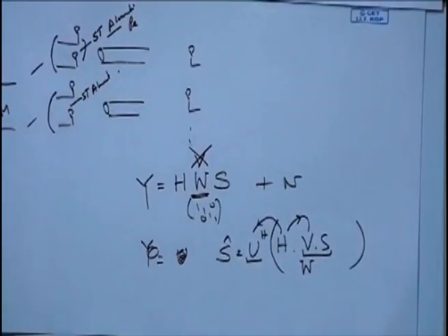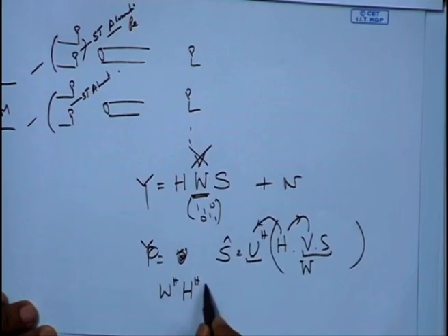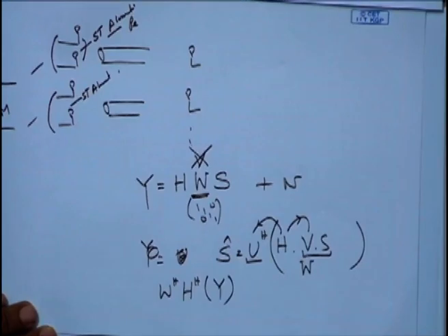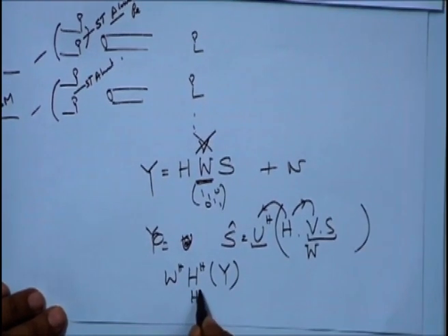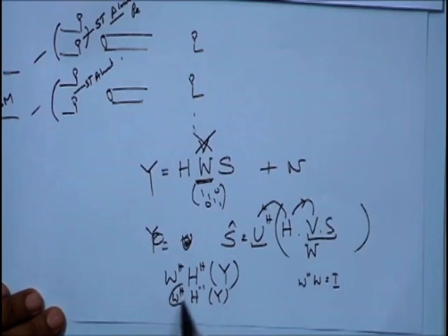At the receiver it is not a problem, because one of the easiest ways for a receiver is to multiply H Hermitian and then W Hermitian to Y. The other way I could do it is H inverse times Y times W Hermitian, and I would ensure that W Hermitian W is equal to identity. So, in this way we have predefined matrices.